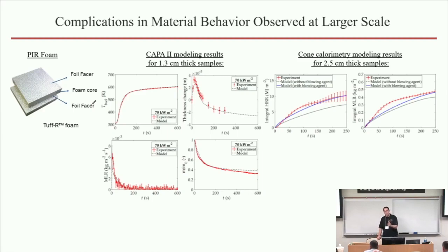So once you look at the low density, low flammability matrix, and you just add a little bit of gaseous agent, it actually has a pretty profound impact on your heat release rate, right? And it's right here. When you include the appropriate amount of this gaseous agent in the model, you actually hit the integral heat release rate, and without it, you don't. And in the sample that we examined in the calorimeter, we didn't really have any gaseous agent left, because when you cut it to that thickness, most of it actually goes away. So this is something where you wouldn't think off the top of your head that you would lose that feature of the material when you're doing that, but in fact you do. And it has an impact that makes a difference, right?